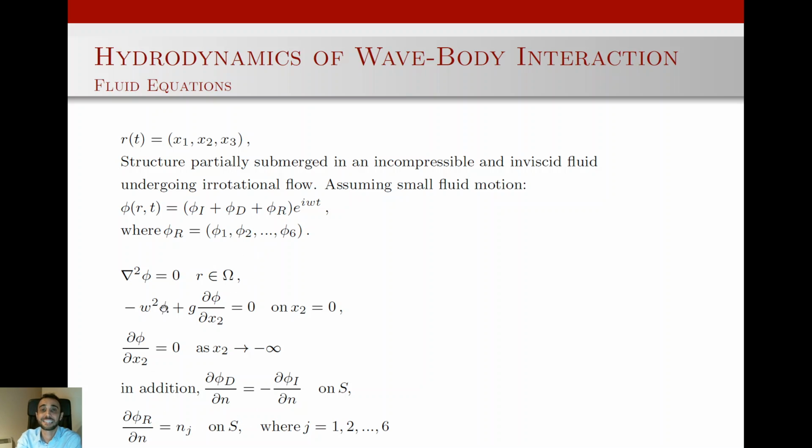Therefore, we create this system of equations, in which the domain equation is Laplace's equation, subject to the time-linearized free surface boundary conditions, combined kinematic and dynamic free surface, and the no-flux boundary condition on the seafloor. It could be deep water, or in general x2 going to minus h. In addition, on the body boundary, we have a condition that the diffraction and incoming potential should satisfy, and also the radiation potential should satisfy this condition.